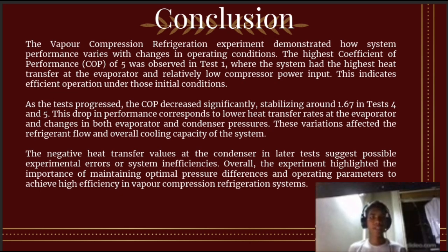In conclusion, the vapor compression refrigeration experiment demonstrated how system performance varies with changes in operating conditions. The highest COP, coefficient of performance, of 5 was observed in test 1, where the system had the highest heat transfer at the evaporator and relatively low compressor power input. This indicates efficient operation under those initial conditions. As the test progressed, the COP decreased significantly, stabilizing around 1.67 in tests 4 and 5.